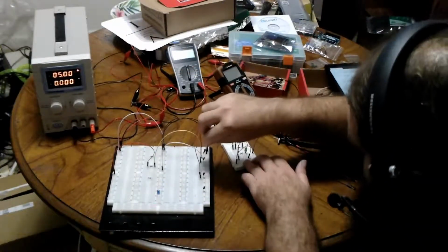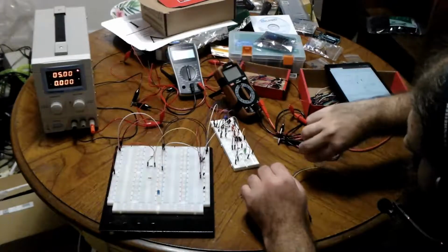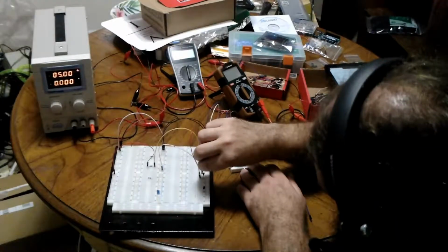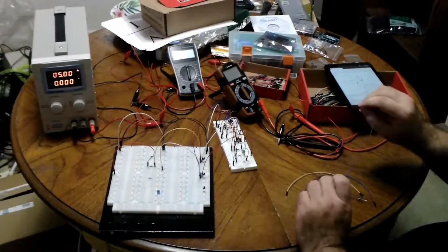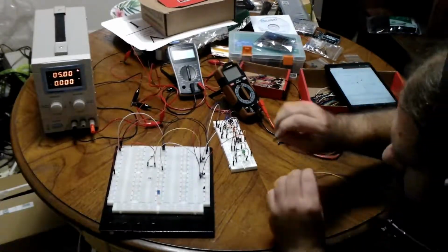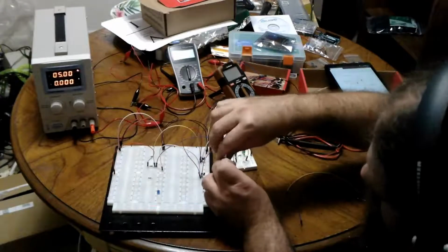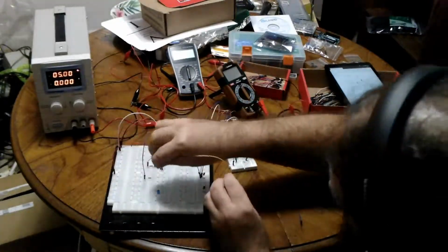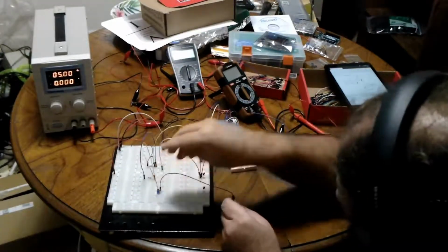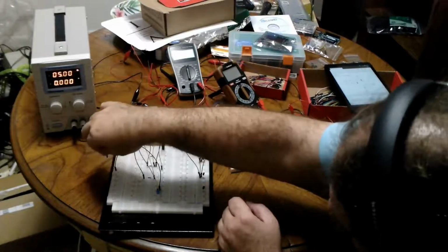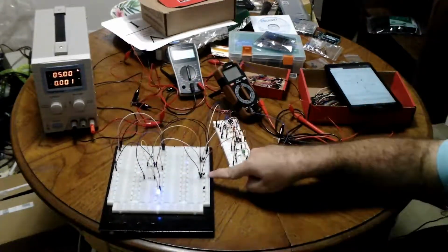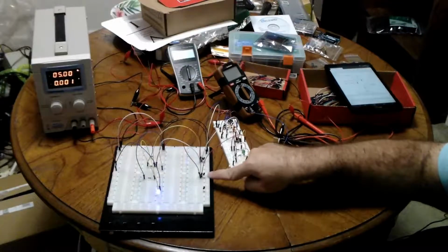Input 1 into the base of one transistor. Input 2 into the base of the other transistor. Then we'll wire it up. We measure between the resistor and the two transistors. So the output here goes to the LED's resistor, from there to the LED, and out. And I got to move this over because I screwed that up. Now it works. These two power rails are separate in this one for whatever reason.